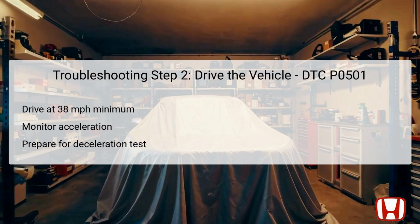The second troubleshooting step requires driving the vehicle at a speed of at least 38 miles per hour, 60 kilometers per hour. This speed ensures that the CVT system operates within normal parameters and allows the diagnostic equipment to collect pertinent data regarding speed sensor performance. During this drive, it is vital to smoothly accelerate to maintain a constant throttle position to accurately test the response of the CVT speed sensor.